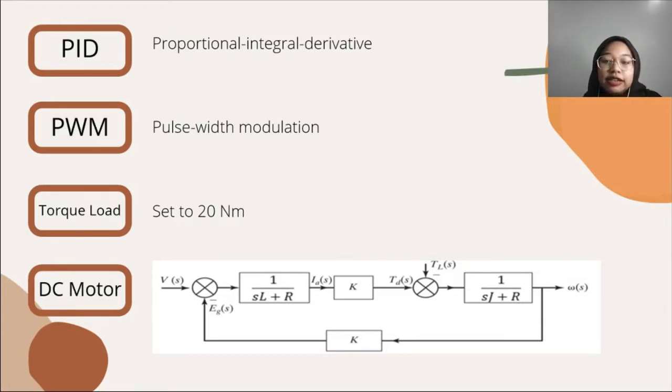0.214596, and the value of current we set to 5.26647. And the last is duty cycle, we just set it to 0. The next part is PWM, which is pulse width modulation. This model uses control PWM voltage and H-bridge blocks to control a motor.